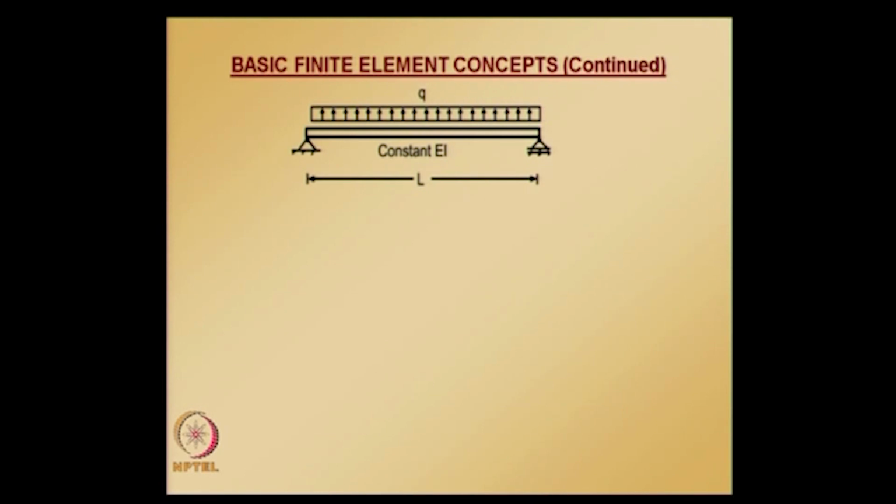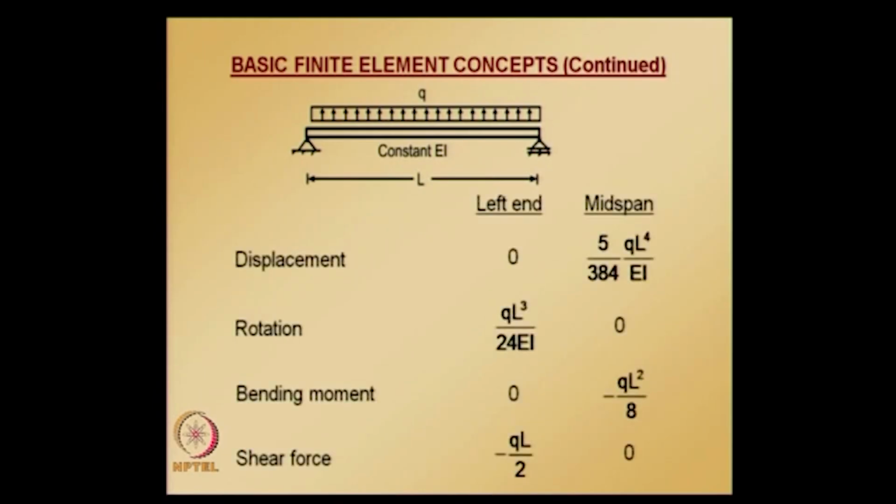The exact solution for this problem is well known and is available in elementary mechanics of materials books. The transverse displacement at the left end is 0, and at mid span it is 5 QL^4 over 384 EI, where Q is the distributed load.